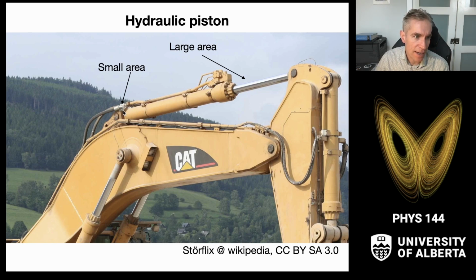And this tiny little pipe presses fluid into this piston. And so it exerts a force per unit area, or a pressure here. And then that pressure has to push on a larger area to force this piston there. It forces the piston to extend.